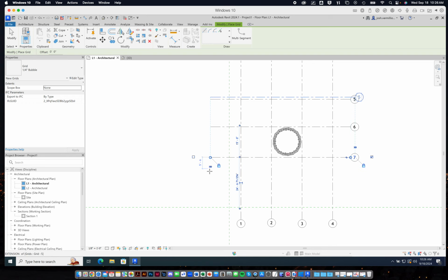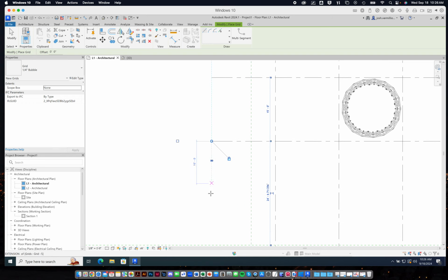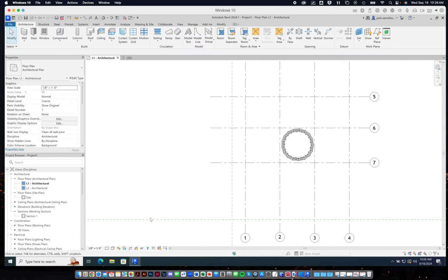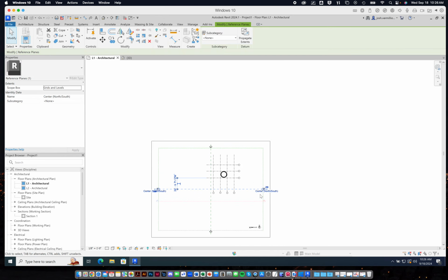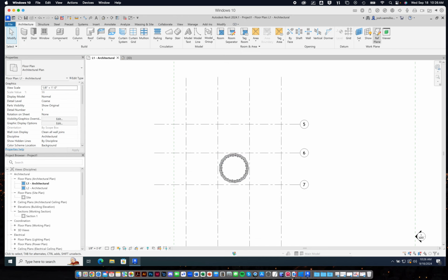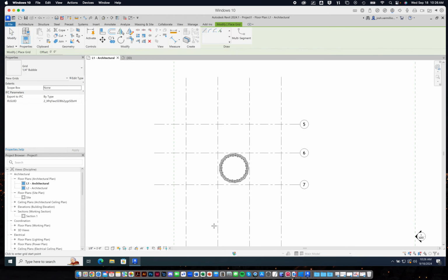And look at this. Isn't that annoying? You get further away and you get closer to this line, and then it only tracks from that line. So what I'm going to do is just go back up to this arrow, just move this stupid center line down and away. We don't really care. For our purposes, we don't really necessarily need to worry about that. Now go back to Architecture tab and the grid, and we'll go down 15 feet and we'll establish a grid.